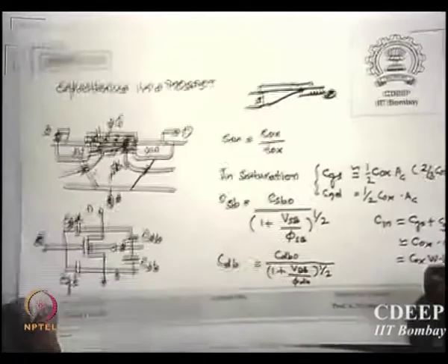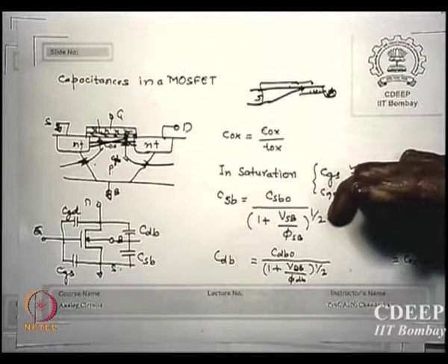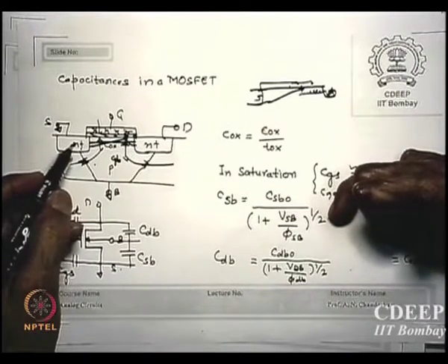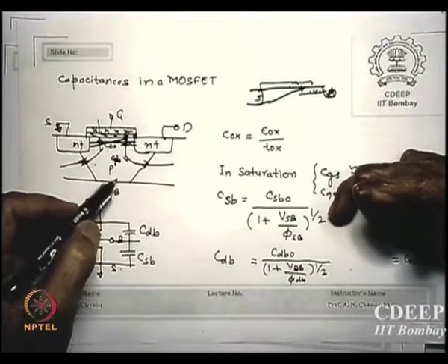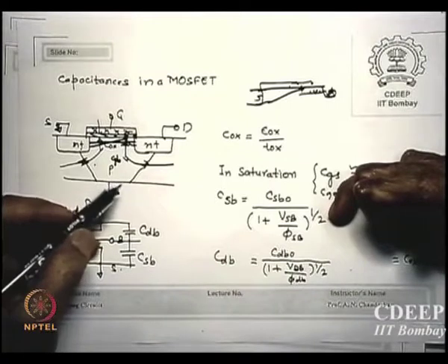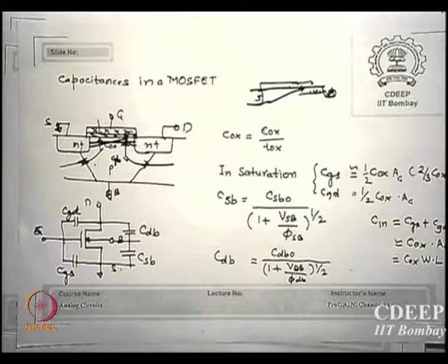Because, your point, since the channel exists here, it is screening the bulk. The channel has a large number of electrons, one side is connected to the source, so the plate is already made available to Cox. There is a resistance here which you may object to. The semiconductor resistance is in series there, but we are anyway saying it is much smaller, because the area of the wafer is very large, so rho L by A.